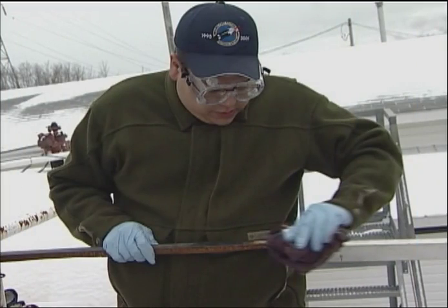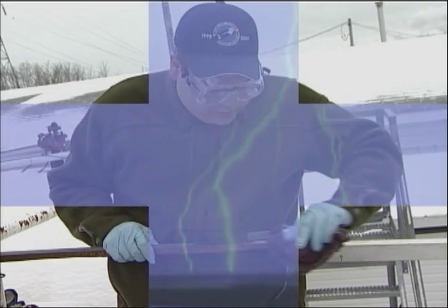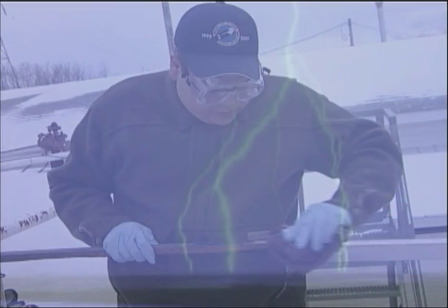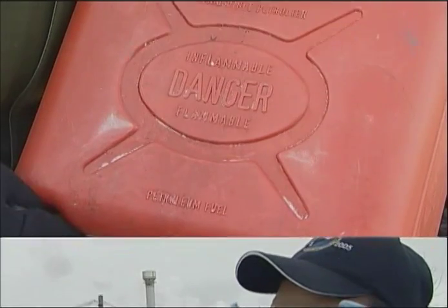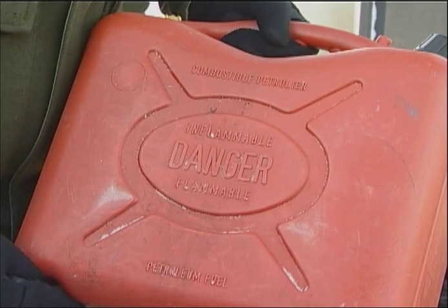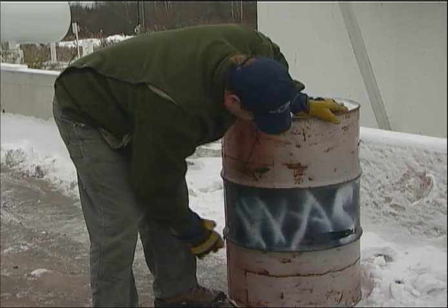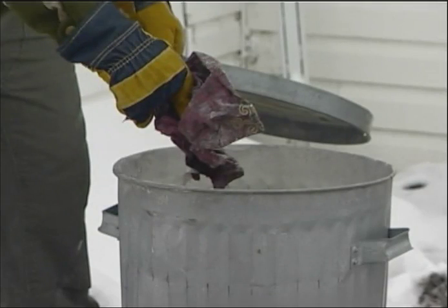Never expose skin to petroleum products. Avoid wearing nylon clothing, pants, or jackets, as that type of clothing generates static electricity, which could cause a spark. Practice first aid if products should touch skin or eyes. Never inhale or ingest fuel or vapor of petroleum product. Keep your fuel tanks and dispensers clean of garbage and/or hazardous matters.